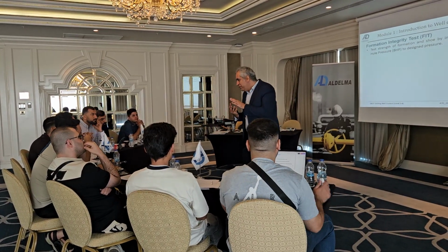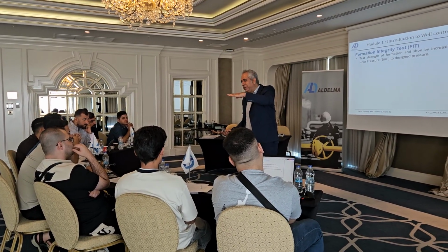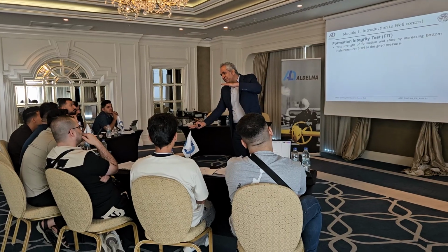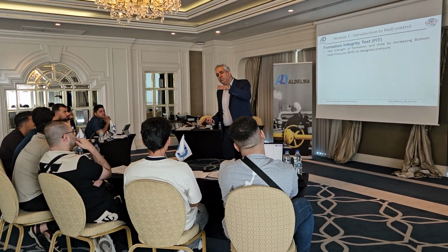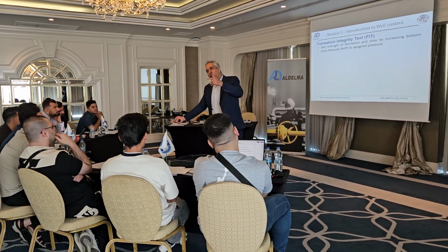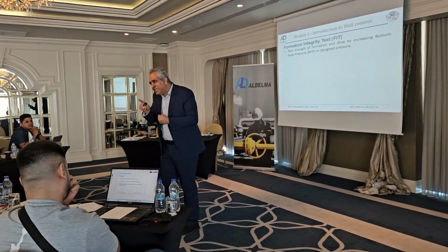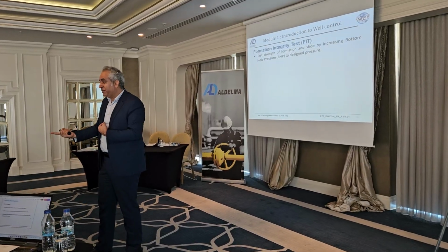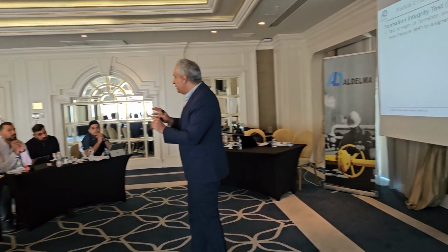We want to see, okay, if I'm right now at 2000 meters and I want to go to 3000 meters, and I know that based on the plan or program I need to increase the mud weight from 10 to 13 ppg, what I do with the FIT is use 10 ppg and apply surface pressure, and make an equivalent mud weight of 13 ppg at the shoe before drilling. This is the FIT. When I do this, I'm double checking the program, whether it is working or not.